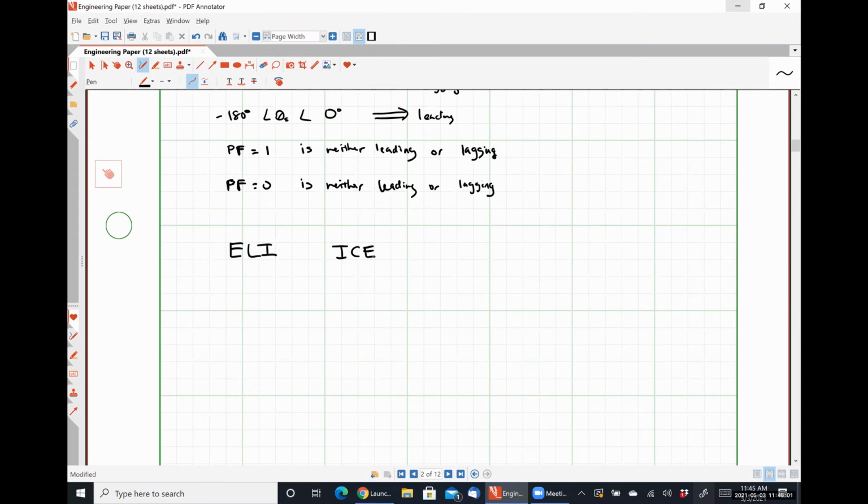I didn't learn that until I was in graduate school, actually until I was teaching Circuits 1 with somebody else who had gotten their undergraduate degree in India, and it was like, oh, I just remember it this way. I remember it from the sign of the phase angle. The sign of the angle theta S tells me everything I need to know about whether my load is inductive and therefore whether my power factor is leading or lagging. But that is definitely handy, so it's stuck in my brain too. Any other questions with regards to power factor?